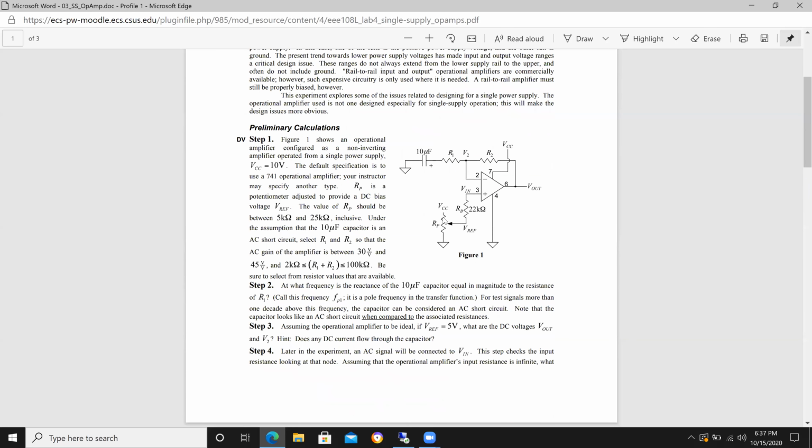That's a true statement. So your impedance from VN seen looking down into here is going to be RB. So here's going to be your equation. It's going to be VN equals RB plus this. This is going to be a parallel resistor. And I'm going to show you on a schematic. I'm going to jump to that right now.